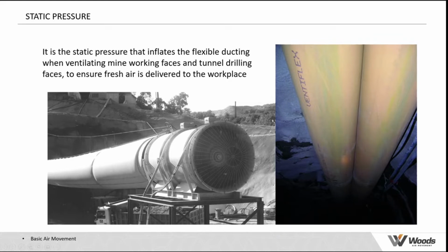If we're digging our hole in the ground, or it's a mine or whatever it is, the people doing that work need to have fresh air delivered to where they're working. That might be several hundred meters inside the tunnel. So effectively what you put on it is a flexible duct, which is no different to a balloon almost. And the static pressure will maintain the shape of the duct while the air goes down it to be delivered to the workspace. So that's a very practical illustration.